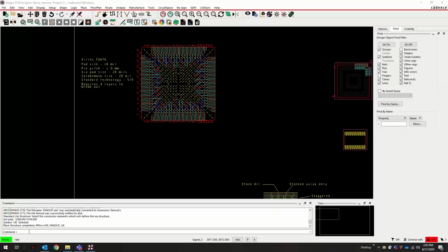Let's see if there are any other questions. Well, here's the last one that we could get: what's the most widely used BGA breakout technique? That really depends on your BGA, where your pins are located and where they're going to feed to the other components. So that's kind of a trial and error thing when you're going for the BGA fan out, depending on where all your blocks of pins are going to be talking to the external components outside. I like the diagonal one the best. It gives me the most options for being able to pull out of there, but it really depends on your BGA.